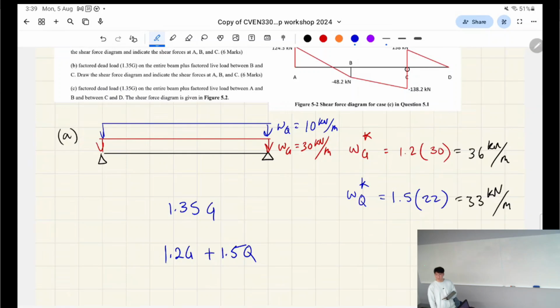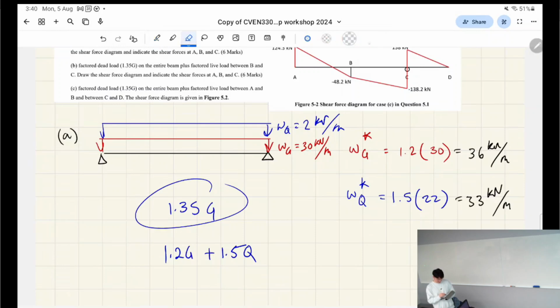Hard to tell, right? Well, it turns out the threshold is that the live load has to be 1/10 of the dead load in order for both the loads to give the exact same number for the case of the beam being distributed over the entire load. If this was less, then this case governs. Do you know what I mean? It's like a negligible live load. Sorry, I'm really nerding into this because this is what my thesis is also about.